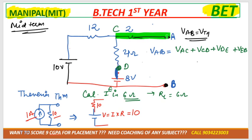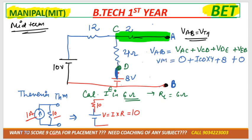In an open circuit, can current flow? Yes or no? It's an open circuit, current can't flow. So if current can't flow, then in that case voltage is 0. Okay? VCD we can write down as ICD into RCD. How much is the resistance between C to D? That is 4. VDE is how much? 8 volt. So we can write it down as 8. VEB is again open circuit, so it would be 0. This is equal to VAB.